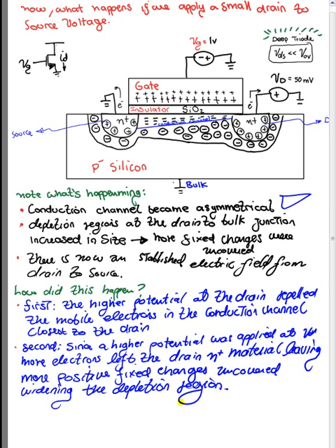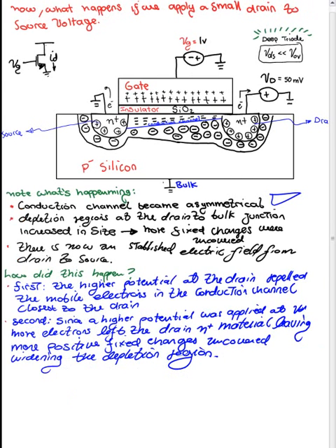Okay, so what we really did here is that we put the transistor into the deep triode region of operation, which we explained before. It's also called the linear resistor-like region, or the linear transistor region, right? Because small changes in VDS generate proportional changes in drain current. So let's write that down.